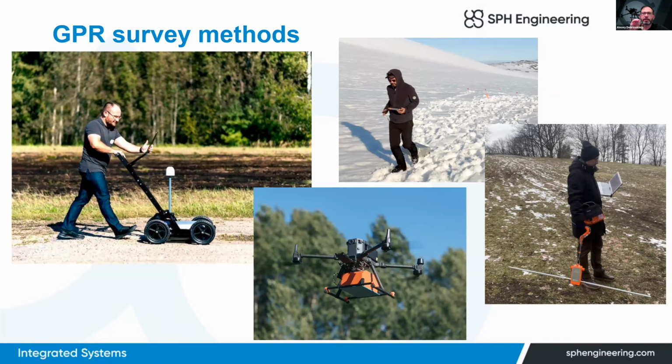Exactly in similar conditions, when we cannot use a cart because of bearing capacity, the possibility to push the cart over snow or over some bog may actually not be possible. In such cases, we can just pack GPR into a box or place it on a sled and drag it.